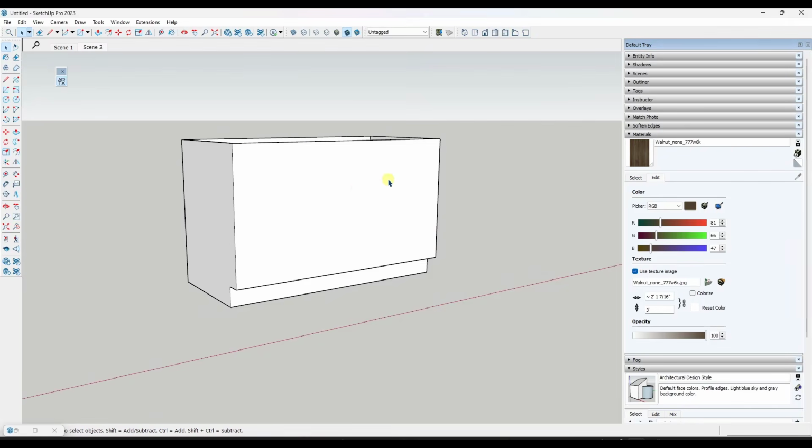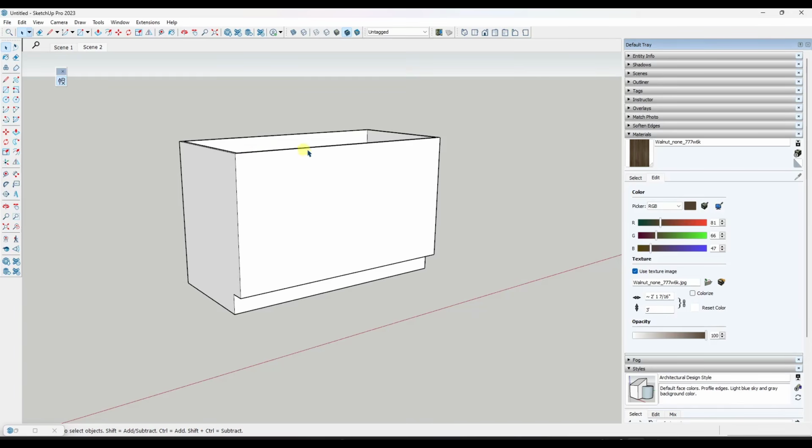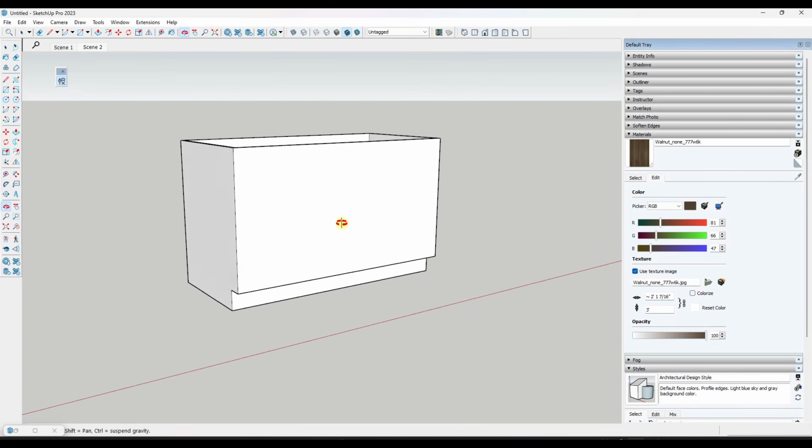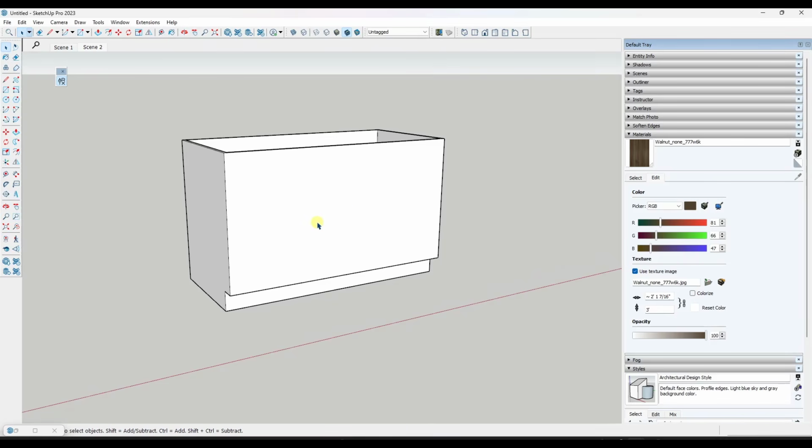But now we've got a wider box in here, and what I want to do is I want to set this up with some recessed cabinets and drawers. And so remember, with the recessed, what happens is you kind of have a piece of trim around, kind of framing out where those openings are. So in this situation, what I would want to do is I would want to kind of model out that frame first. So I'm going to draw a rectangle across this face, and I'm actually going to right click and hide this cabinet just because I feel like it gets in the way.